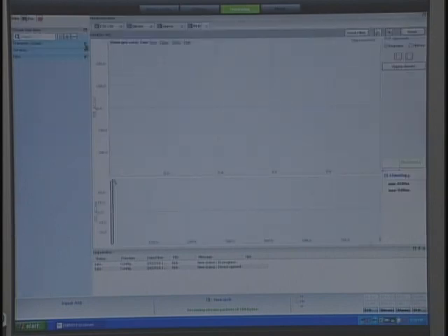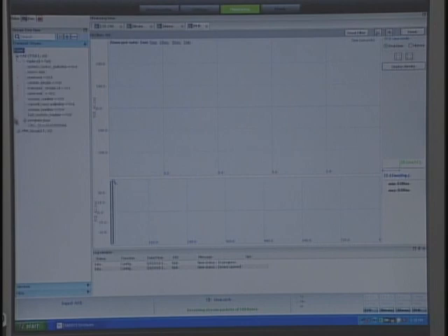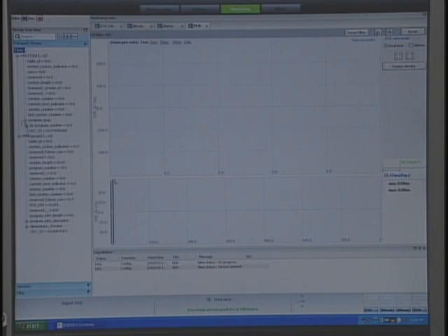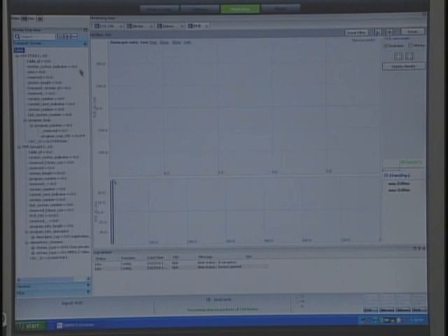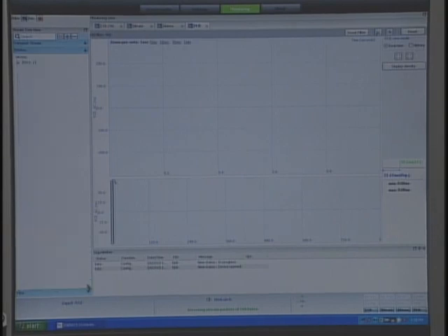If you open these up on the transport stream, you'll see what your ASI is that's coming in, and you can open up these little sections in here and get a little bit more granular into what's coming in. And you'll see the tables, sections, and all the different parts that make up the transport stream. Under services, you'll see that you have an MPEG-2 video PCR in there. Under PIDs, you'll see the different PIDs that are in here.